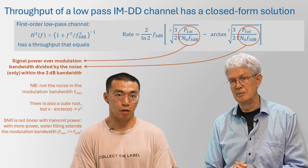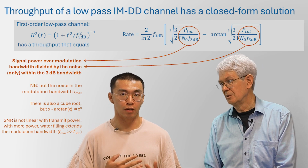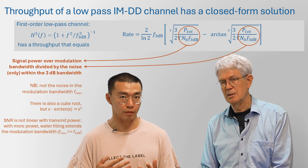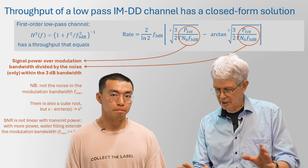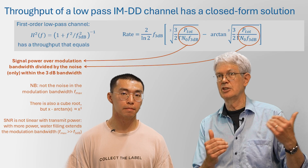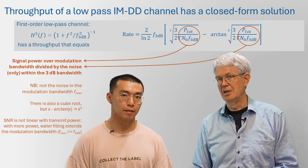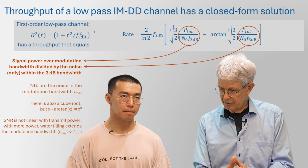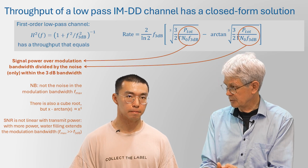Which also makes the point why we are not using the signal to noise ratio as a metric to estimate the throughput. I've seen that a lot in papers. Systems are compared for the same signal to noise ratio, which sounds like an apples to apples comparison. But in fact, it is not, because we can play with the bandwidth, which is a design optimization, and two different systems may have two different optimal points.